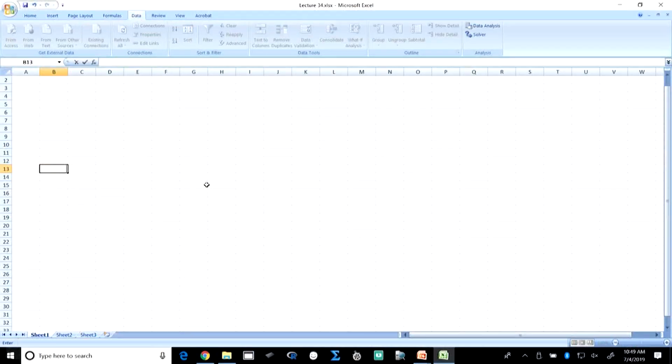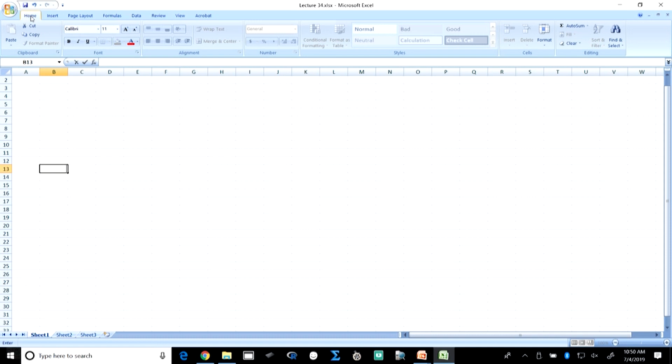So you go to the initial Excel sheet, and through that you go to Add-ins, where the Solver add-in is available. You can run that add-in, and the Solver tool will appear under the Data tab.